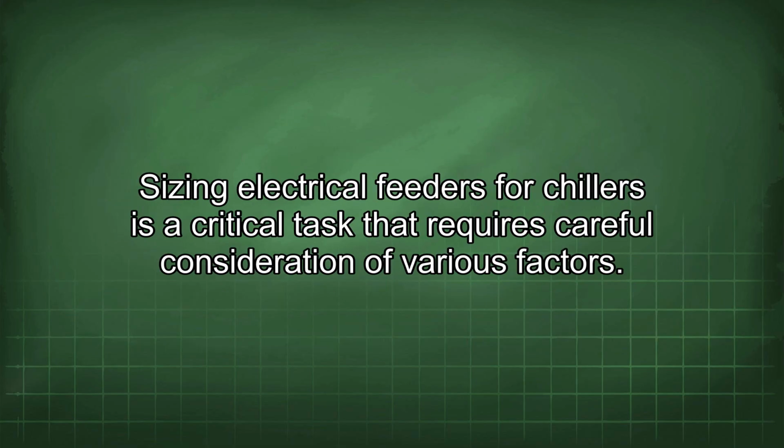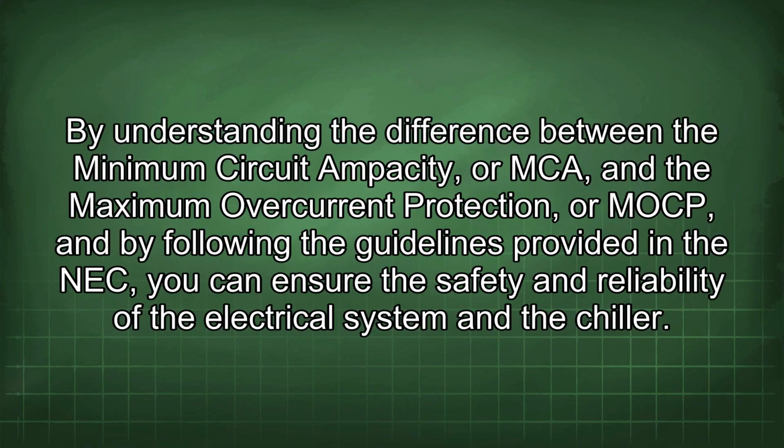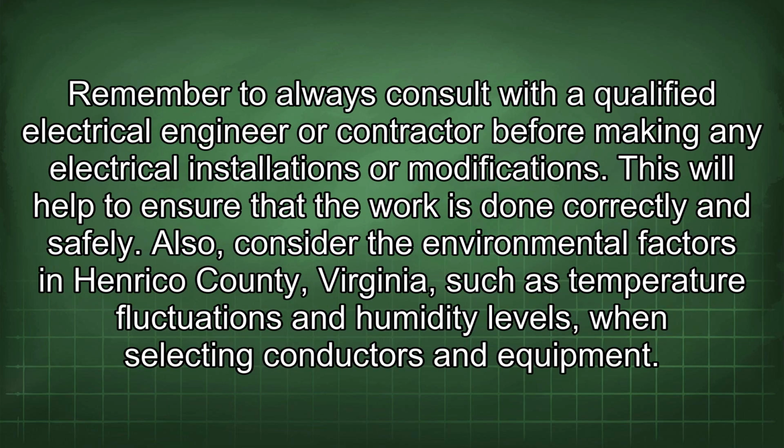Sizing electrical feeders for chillers is a critical task that requires careful consideration of various factors. By understanding the difference between the minimum circuit ampacity, or MCA, and the maximum overcurrent protection, or MOCP, and by following the guidelines provided in the NEC, you can ensure the safety and reliability of the electrical system and the chiller. Remember to always consult with a qualified electrical engineer or contractor before making any electrical installations or modifications. This will help to ensure that the work is done correctly and safely.